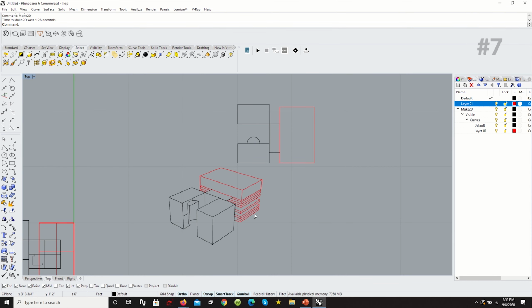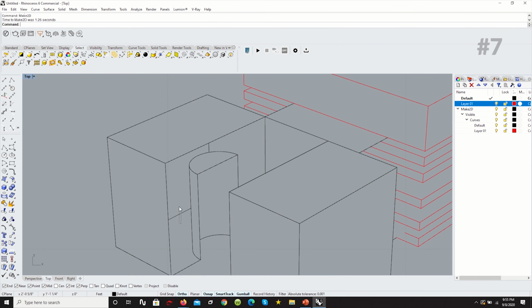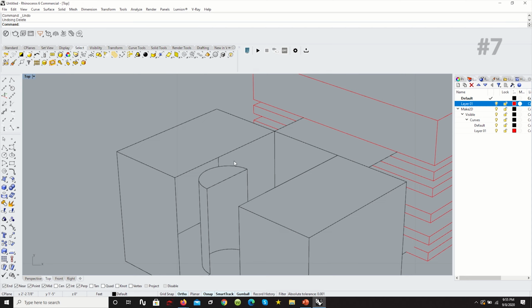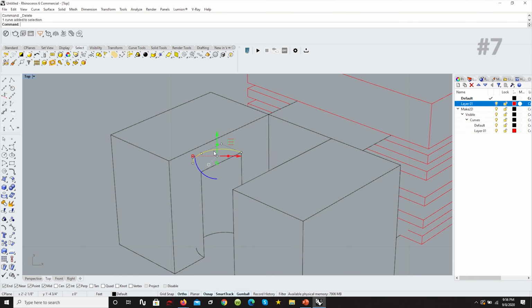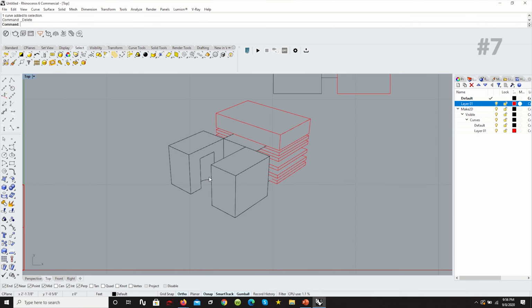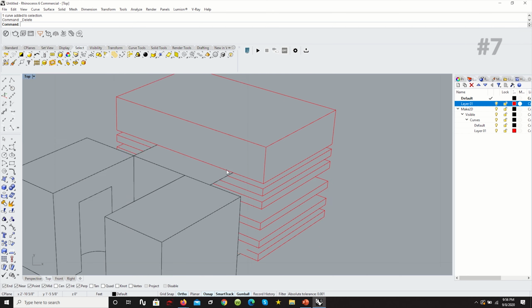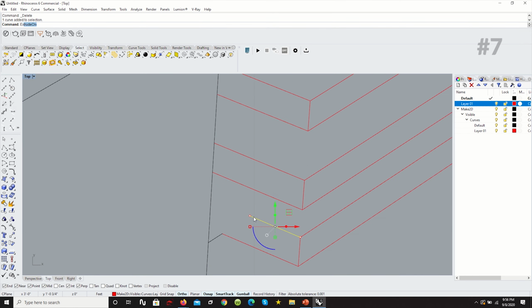Just because you made a make 2D of the model, it doesn't mean this is the end. You can always go back in, clean it up, and join certain lines. I'm going to make a future video talking about the workflow going from Rhino to a program like Photoshop or Illustrator, to do further entourages and to liven up your drawings. We can even go in here and delete some of these objects. These lines will basically be invisible. If this is solid, it'll be invisible. You could go in there and clean it up a bit. Type EXT, for extend. You can extend some of these lines.